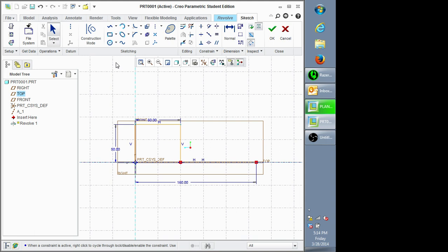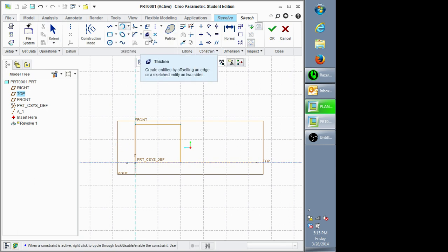To create the curve part of the nose, we want to go in and select this. If you go over here to this tool, you have several options to create different kinds of curves. You can create rounds using this tool, and all these different options. Let's select this tool right here, this 3-point tangent end. It should be the default for that tool.